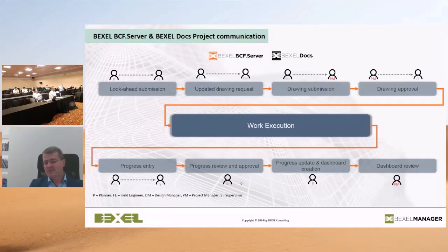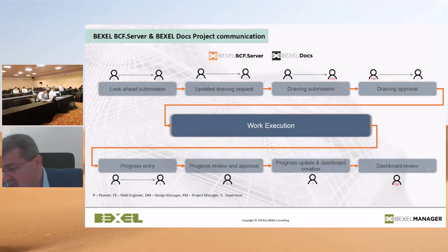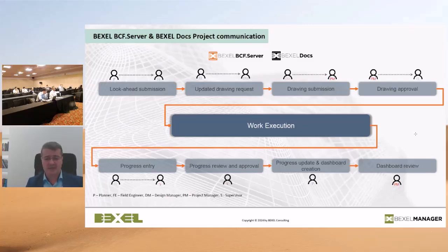The progress is automatically updated in Bexel Manager, and the planner creates a new updated progress which includes a baseline schedule and an actual schedule, and then the reports are automatically published and submitted to the project management team so they can review the works on the site, and it's done on a weekly basis. It could also be on a daily basis, or on a monthly basis, but in this case, the client decided that the weekly interval is optimal for them.